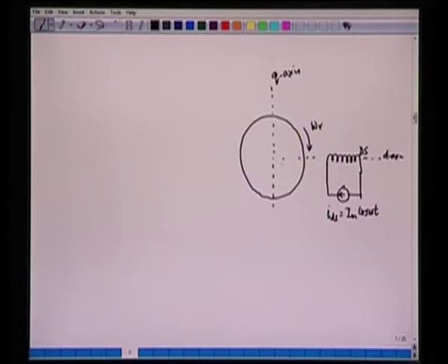The winding which was aligned with the stator at t equal to 0 has now moved to a different position. Now if I see the new position of the rotor winding, the new position will be somewhere here. So this is dr, this is the winding, that is dr. Now the dr axis is this. Now this angle between the d axis stator and the rotor winding is now known as theta r.